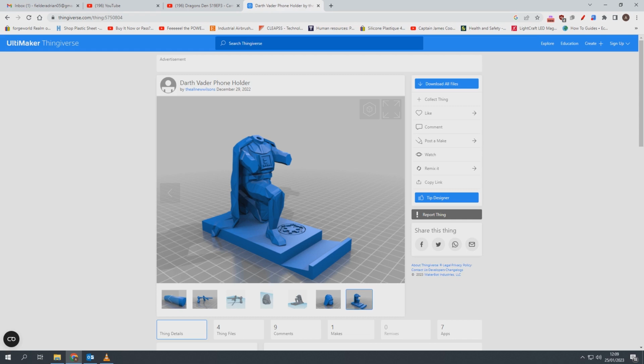because the layer that is being printed is so thin, that first layer, as it works its way round and starts to print the first layer of that arm, it will just flop down. So you'd need supports between the bottom of that arm and the bed or the base. And then you have to cut those out afterwards and make good, basically. But so you do have to understand a little bit.